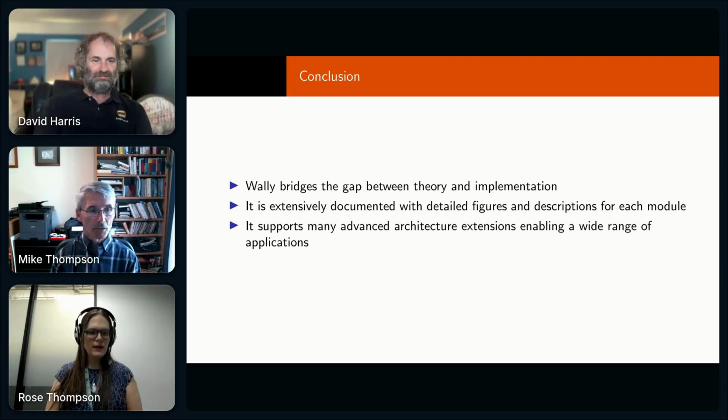the organization you were dealing with, you had persuaded them to look at the vector ISA rather than implement their own dot product ISA. Yeah, so I asked them to look at vector, and their conclusion from that was not only was vector able to provide the same functionality as the dot product, but it is able to vectorize other code in the application. We got a faster implementation of their algorithm using the vector ISA than if they had implemented their own dot product instruction.